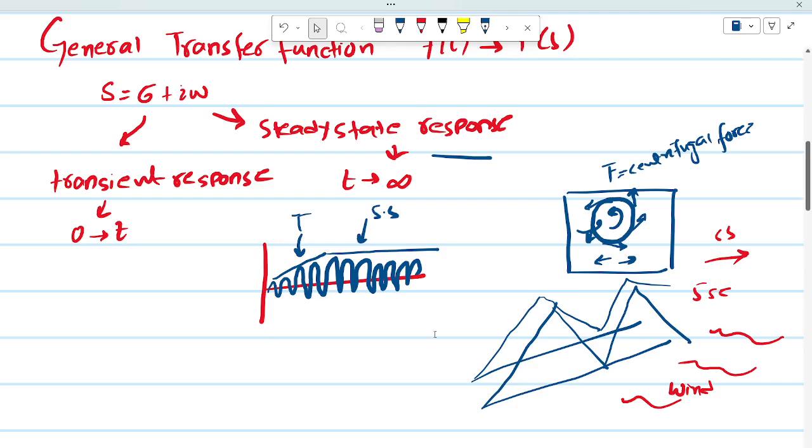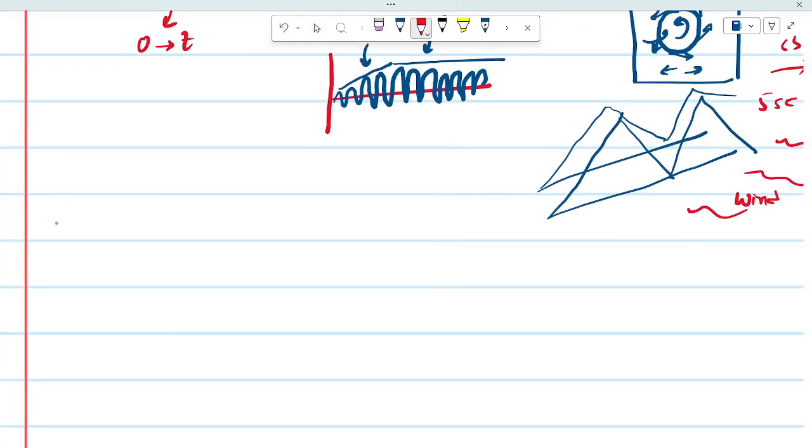So for that, we have a special kind of transfer function that's called the sinusoidal transfer function. So that is termed as the sinusoidal transfer function, and obviously when a sinusoidal input is applied to the linear time invariant system, as we have discussed earlier, that Laplace transformation is applicable only to the linear time invariant system. Even if the system is non-linear, you have to convert that system into a linear system mathematically and then apply the Laplace transformation.